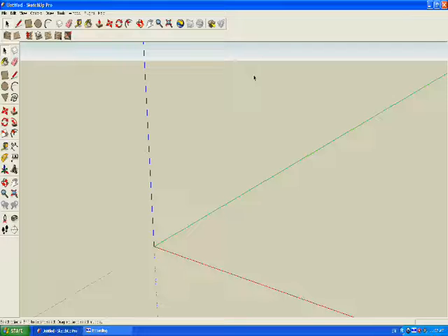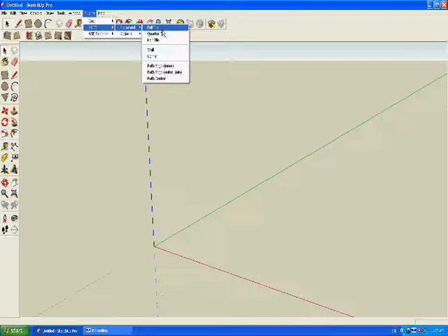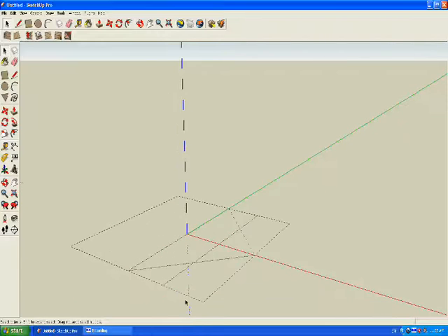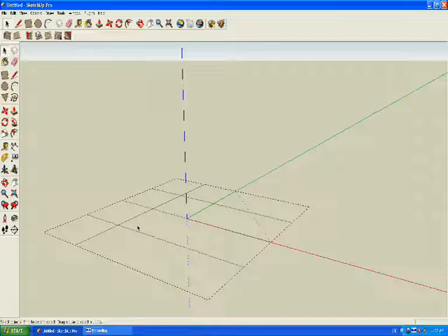Now we need to know exactly where we have to build our object. To do this, go to Plugins, RCT3, Placement, and in here you'll see full tile, quarter tile, half tile, and many others. These will show you, depending on what object, where to build it. In my case, I'm going to build a cube just as an example, so I'll choose full tile. You'll now notice that there are some dotted lines appearing. These are 4 meters by 4 meters, the exact scale of one Roller Coaster Tycoon tile.